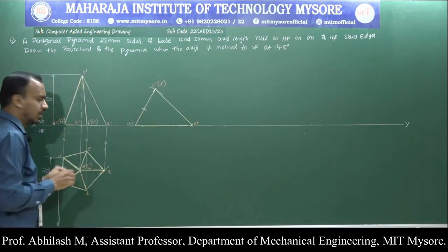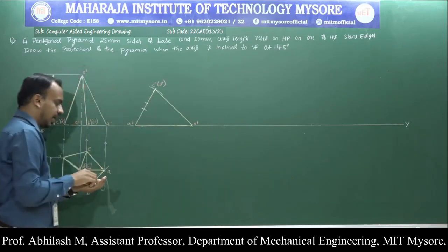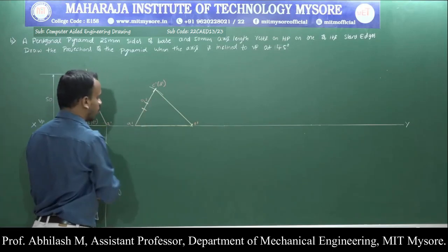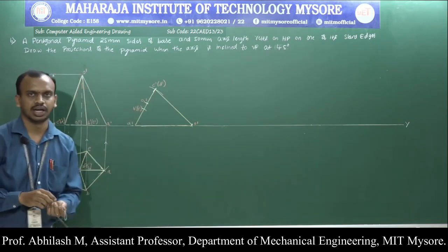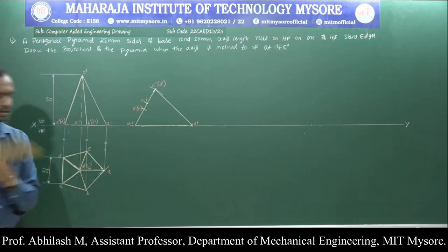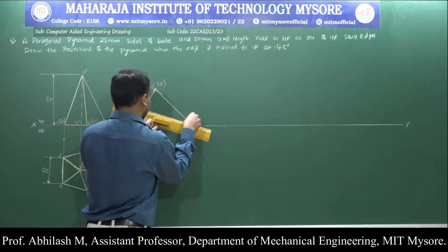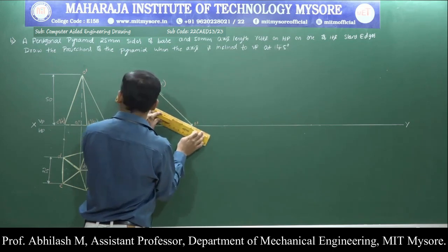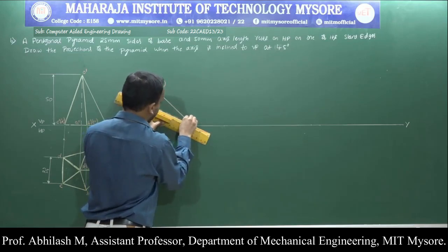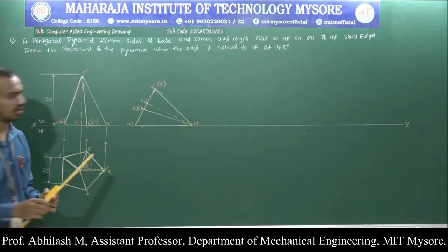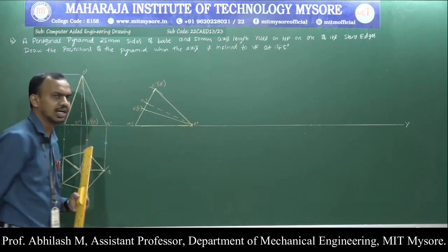I have marked a point. Again from O1 dash to A dash. So identify the point. This point will be my O1 dash and this will be my B1 dash of B dash of E dash. Now complete the process. We are supposed to connect from O dash to the point. Similarly from O dash to O1 dash, it's an axis line. Now we have completely followed the condition that I mentioned. We have rested the entire slant edge on the HP.